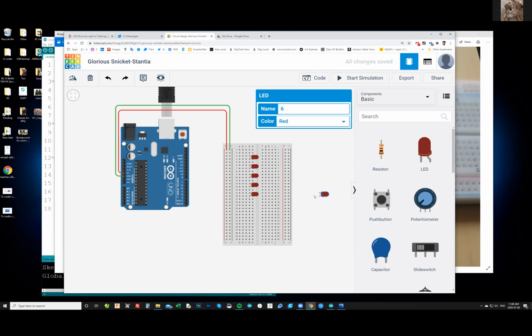You guys can start assembling this. So just note where you're putting the short legs, because that's where the resistor is going to go. And the resistor is going to be in ohms, and we'll use 100 or 220. But do not try to do it in Tinkercad. Do it directly on the board. As Alex wires, now you know how to read the diagram, right? So you can use the actual board and start assembling it there.